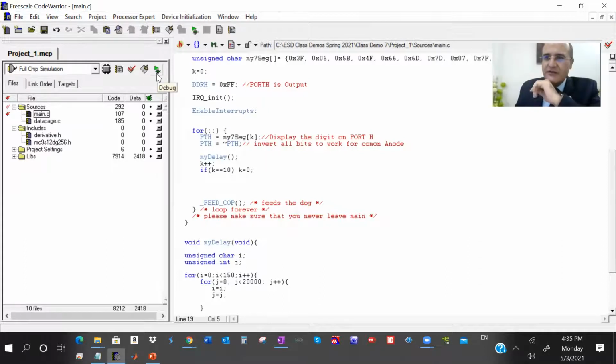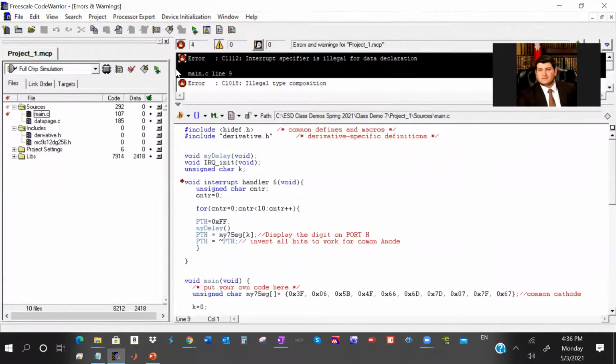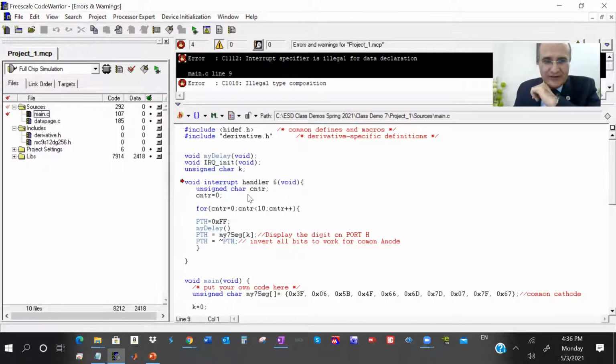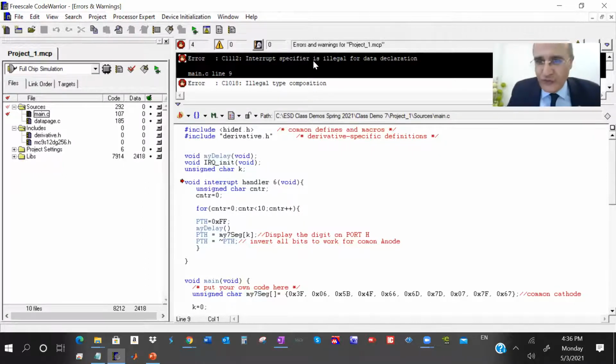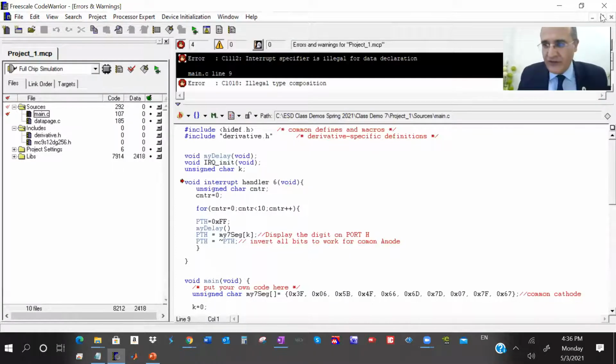Yes. As if the button was connected to E1, like an external push button but the same one installed on the drive. Exactly. But if you don't need a button, you need a falling edge coming from any source, you can do that, right? By just taking the wire, taking it to ground.